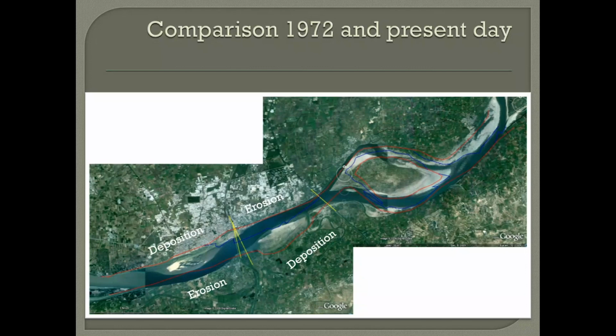And after going through all this simple analysis, it's not very complicated, it's very simple analysis, I came to a conclusion that even if we construct a canal on this part, cutting across the sand, it is not going to survive. I'll tell you why. Because unless and until we change the channel of this part, it will still remain a depositional end for the river. And as long as this part remains a depositional end for the river, whatever channel you make on this sand, the river will be depositing sediments on that channel and it will fill up.